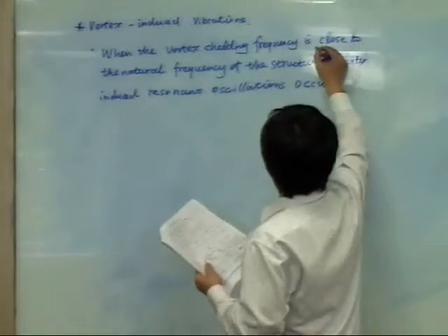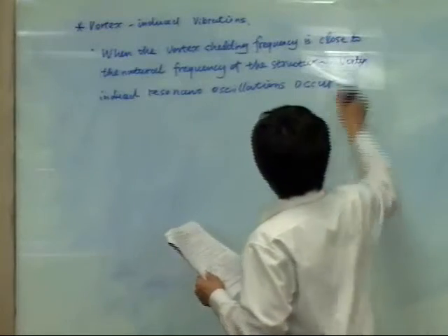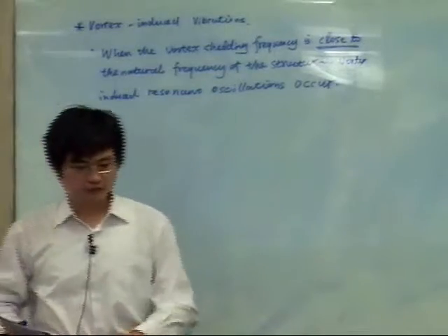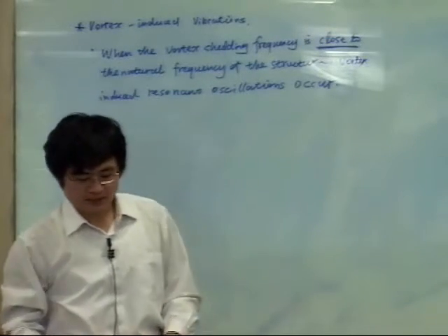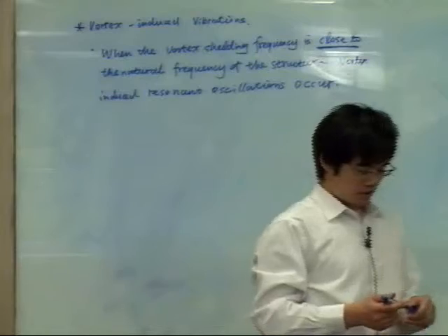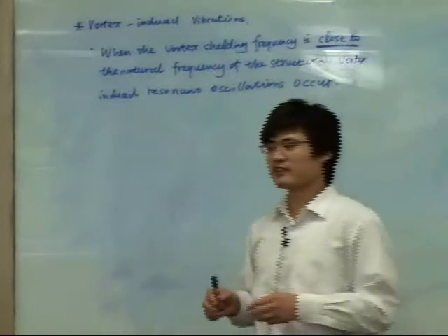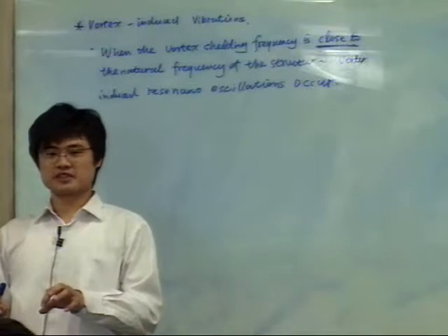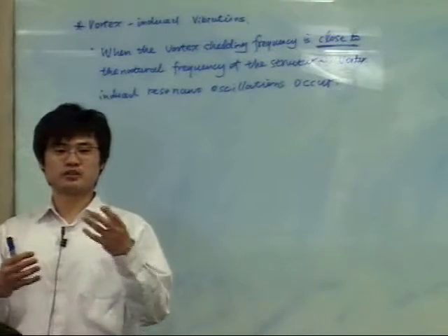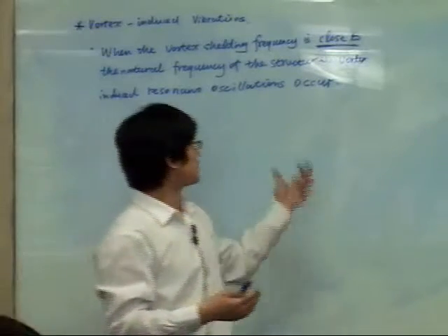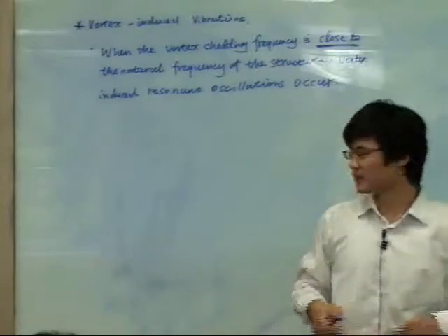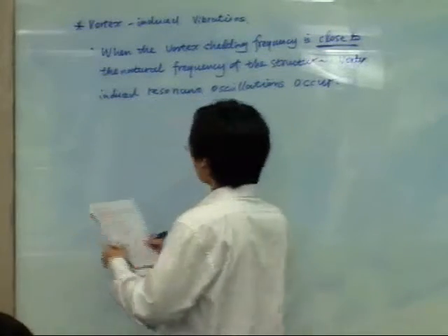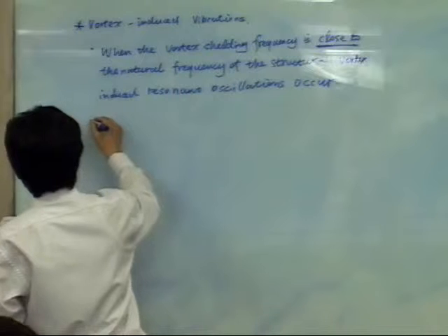Okay, the important thing is close to. We know from structural dynamics when the frequency of the excitation force equals the natural frequency of the structure, we have a resonant response or resonant oscillation. Here in this VIV, we have a special phenomenon called lock-in.